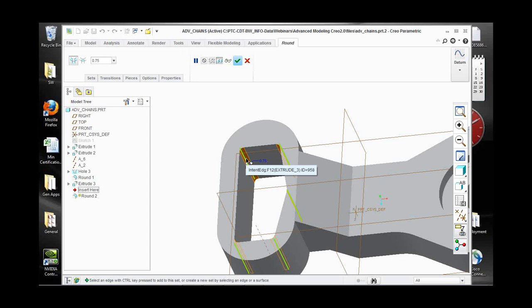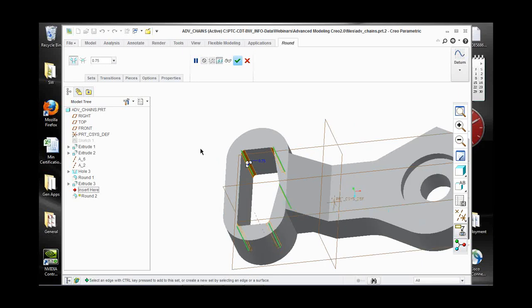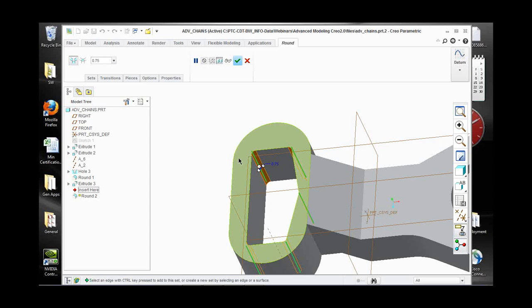In this case, we're not selecting edge IDs. We're selecting the intent of the cutout. Now, here are the rules behind this. First of all, when I go to do an intent edge, notice that when I right-click, I either get all of them or none of them. So I get all 5, I can't pick individual ones, and at this point I can't go back in and unselect individual ones. So that's a little restrictive.